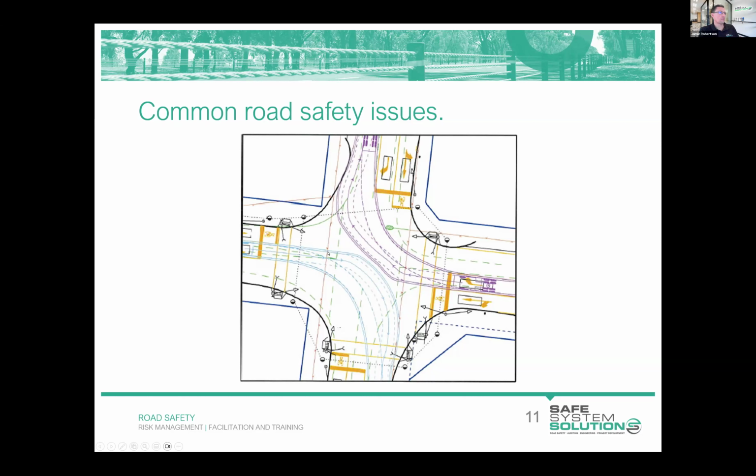The blue path is a better example, with a few little arrowheads there, but you can see that it's a smoother turn, with the widest swept path at around the center of the turn, unlike the purple, which has a varying swept path width because the vehicle's turning, then straightening up, and then turning again.